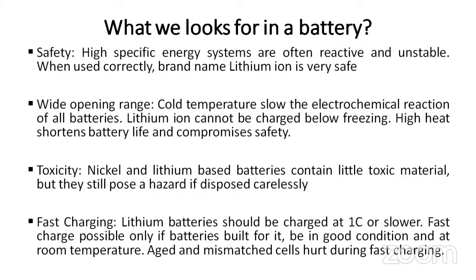Lithium batteries should be charged at 1C or slower. Fast charge is possible only if batteries are built for it, in good condition, at room temperature. Aged and mismatched cells are hurt during fast charging. Okay, so you should take care of all these points to design a battery pack.